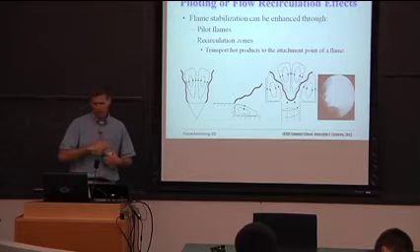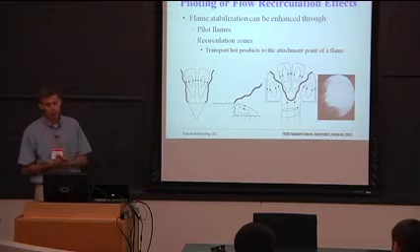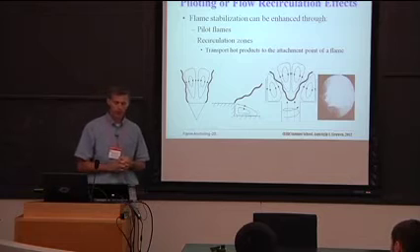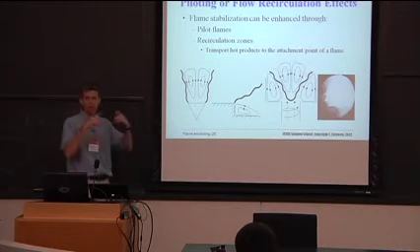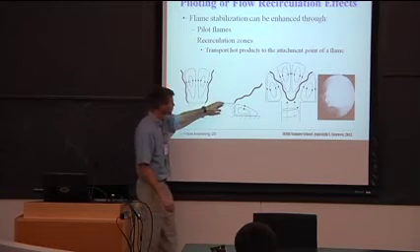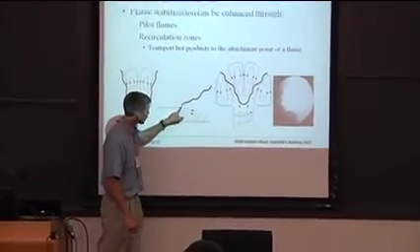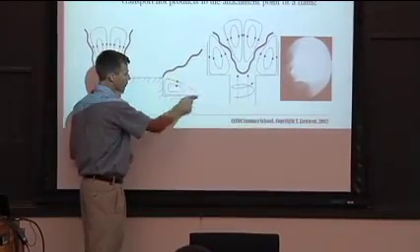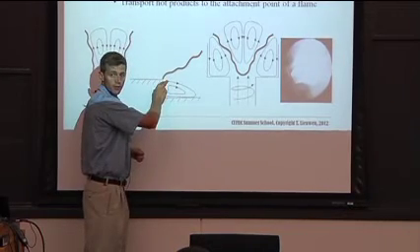All right, I want to add another layer to this flame stabilization issue, which is piloting or flow recirculation effects. Oftentimes to stabilize flames in high velocity flows, you either force some flow recirculation or you put an external pilot in. For example, this is what's called a dump combustor. You force flow separation. Here's your flame, and once you initiate combustion, you have hot products continuously being recirculated, and those products are continuously reigniting your reactants here.